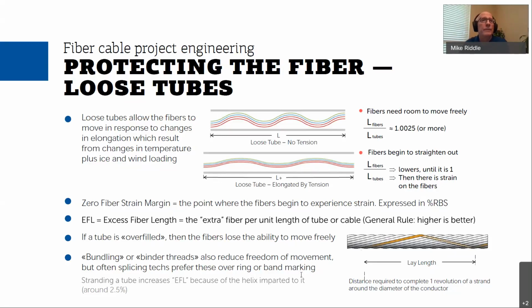In theory, you might wonder about the black fiber. What do you do with it? In theory, you would use a white marker instead of black, because obviously black on black is not going to show up, or you might use yellow. But in reality, in production, that's not really so practical. So most suppliers will just leave the black fiber uncolored with the ring marking on it.